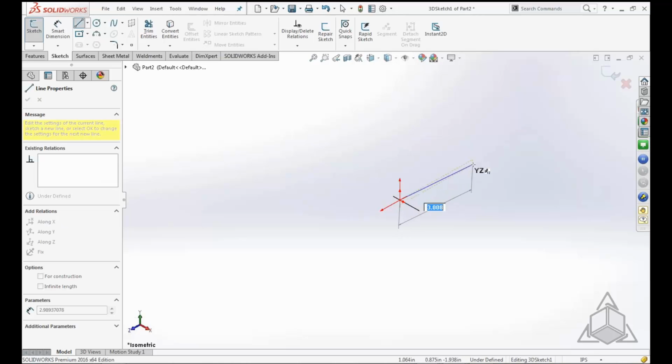And when I go to move my cursor off the space handle, it's kind of hard in this isometric to tell really where I'm going, right? But I do know I can only go in the Z and the Y direction. Y I know is up because of my coordinate system here, and Z is back here.